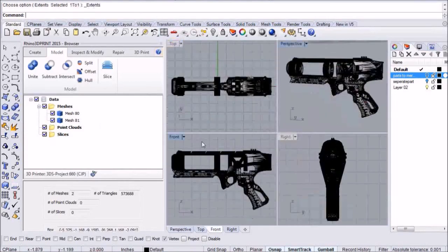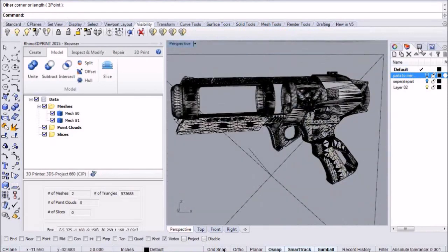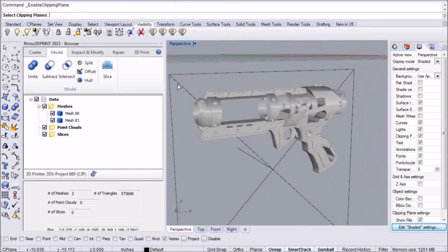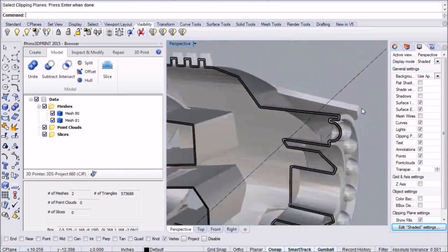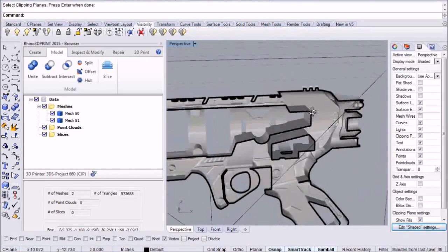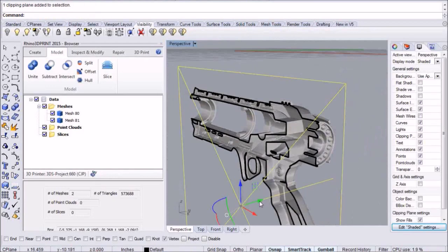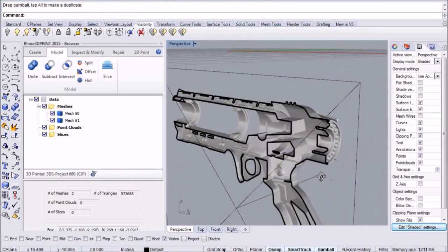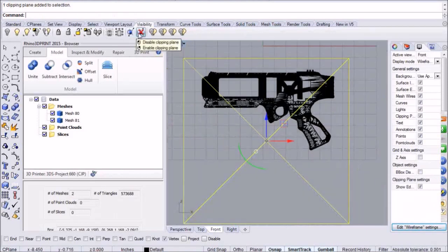Now let's go ahead and analyze this offset mesh in Rhino by creating a section view. So I'm going to go up to the front view in here, and I'll create a clipping plane. We'll insert a clipping plane in Rhino. And let's go over to the perspective view. I'm going to go ahead and hide the mesh wires in here so it's easy to view the model. And let's enable the clipping plane by selecting the clipping plane right there. Now there's your offset mesh, and you can see the two meshes as you view the model. So you can see that all the different individual meshes were united, and then it performed a complex offset of the mesh geometry. You can also move the clipping plane around to view it parallel to the active clipping plane that you're at. Let's go back and disable the clipping plane, and I'm going to go back to the front view and do the same process to disable the clipping plane, and we'll hide it.